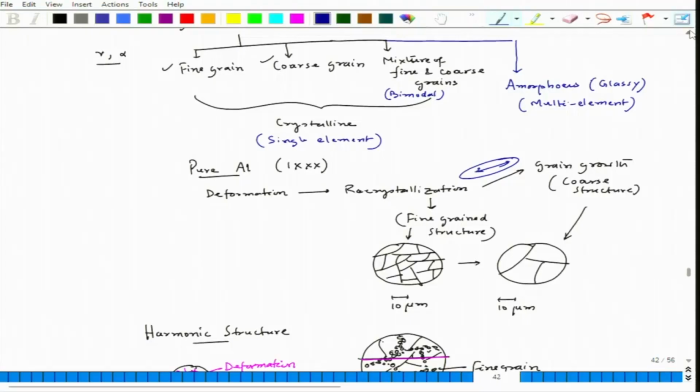data. Okay. Now, we will talk about this fine and coarse grain. Generally, theory shows that when you have a grain structure, the grain boundaries are the regions of higher activity, so they should get attacked first.